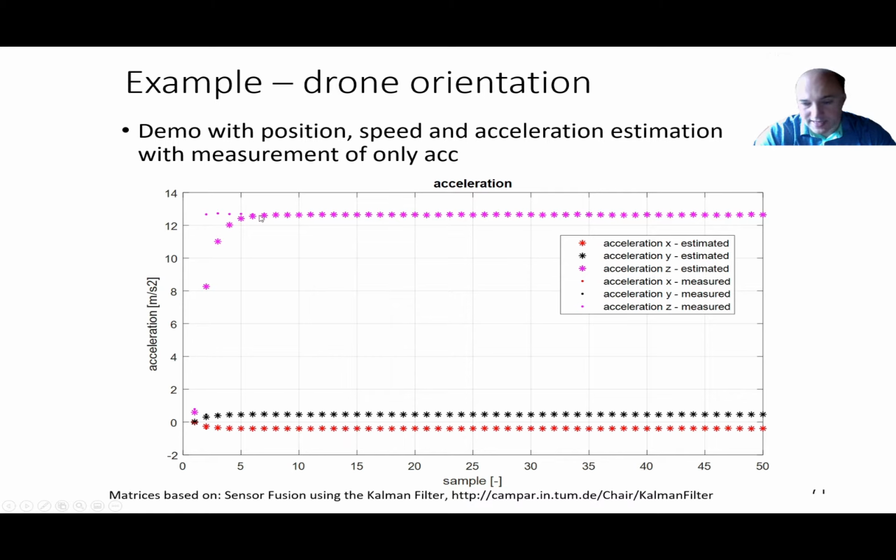So this is telling me that the accelerometer is not calibrated, and if I would like to calibrate it to get real data, I would need to measure it when it's standing still, and then divide it by the value to get the real acceleration that I expect, so 9.81. But for the purpose of Kalman filter, it doesn't matter at all if it's calibrated or not. We see simply how well this is able to follow the constant value.